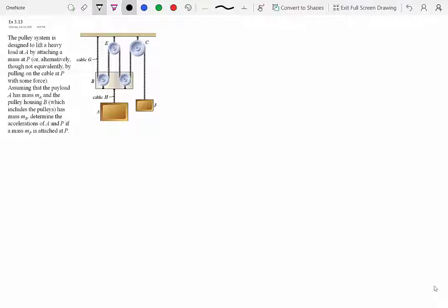The only difference would be that if you pick more than one particle, you would draw a free body diagram of that system where the two particles are together, and you will not show internal forces in the system. And then accordingly, you will write your Newton's second law. If you choose to draw free body diagrams of individual particles, then you can write Newton's second law for individual particles. So you'll essentially be repeating the same thing for multiple particles.